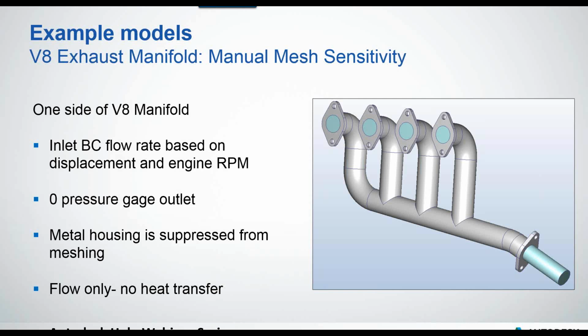One thing I want to note is the geometry, I wouldn't consider simulation ready, but I knew from the beginning I was going to suppress it. So all I care about is basically the air volumes there. So I don't care about those bolt holes or whatever. It's all going to be suppressed anyway. And I didn't do any heat transfer. It's not really the point here. That would probably be transient. It's not really the focus.